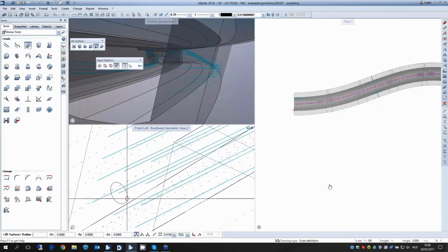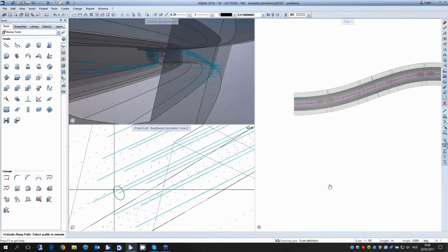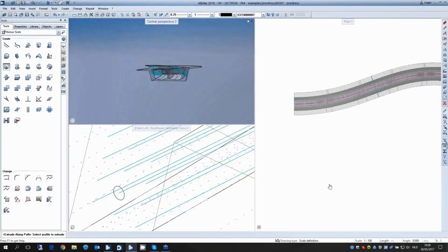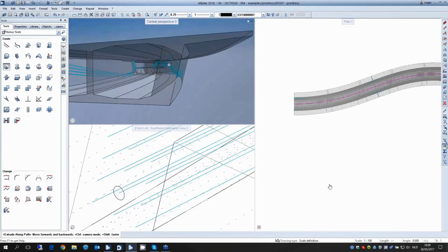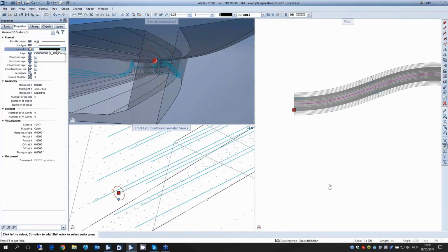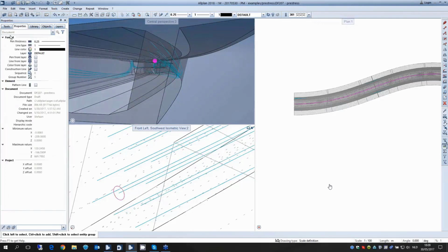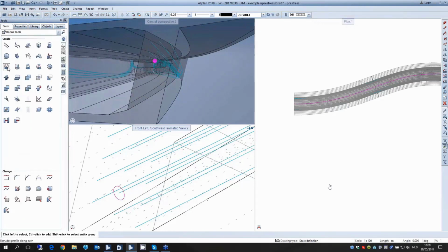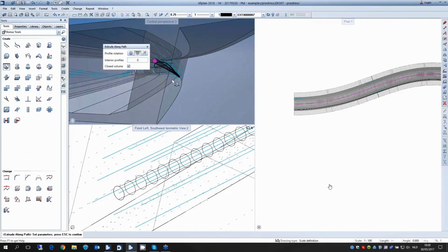And so you can see we're just defining a circle along the length of that spline. We'll go ahead and put it at the end of the spline, create it to the diameter of our liking, and then go ahead and use our extrude tool to run that along the path. And once we execute that, you'll be able to see that it's following that profile correctly. Just got to be sure that we click the profile and then the path, and now it's modeled in 3D.